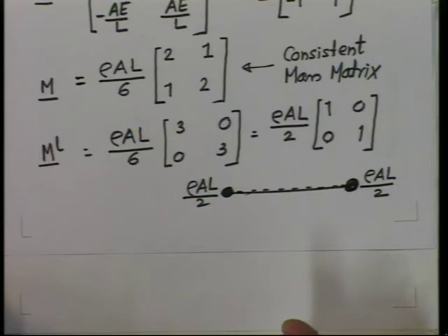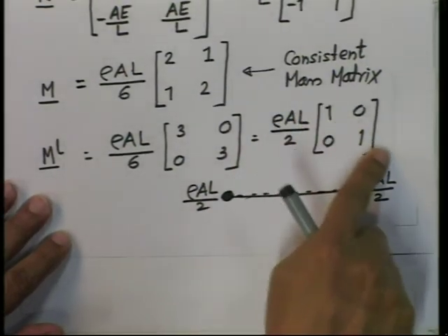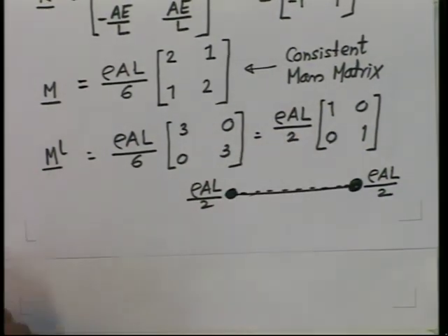Now, it is a 4 by 4 matrix. Obviously, each term has a different dimension, so dimensionally it will not be correct to do it simply. So, blindly it cannot be done. In the diagonalization process, you have to see that mass is always conserved. For example, here diagonalization is making m by 2, mass by 2 at the 2 nodes. Mass of the element must always be conserved. Whatever you do, you should see that mass is conserved.